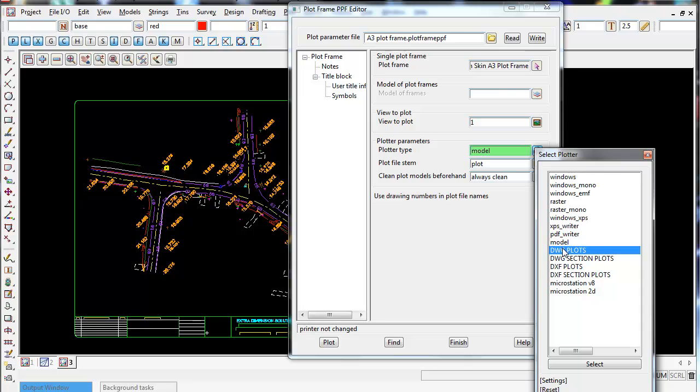Just remember when you plot to AutoCAD though, you will lose the coordinate system this data is in, and also all the data will be in one layer inside AutoCAD. Usually plotting to a DWG is good for long and cross sections, but plan views are usually exported using the File IO option, which I'll show you in the next video.